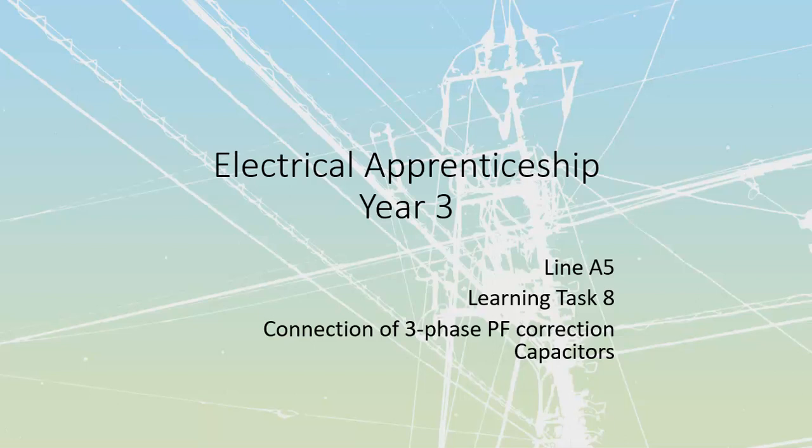A lot of LED lights, because it's a PN junction, act as if they were a bunch of tiny little capacitors. So we can get a leading or a lagging kVAR, or a leading or lagging system, just due to the loads that we have connected onto it. And we want to correct that. It's rare to go leading, to have too much capacitance on the system, but it is very, very common for us to have a lagging one. And if we do have a lagging one, we're going to add kVAR power factor correction capacitors in to fix it up.